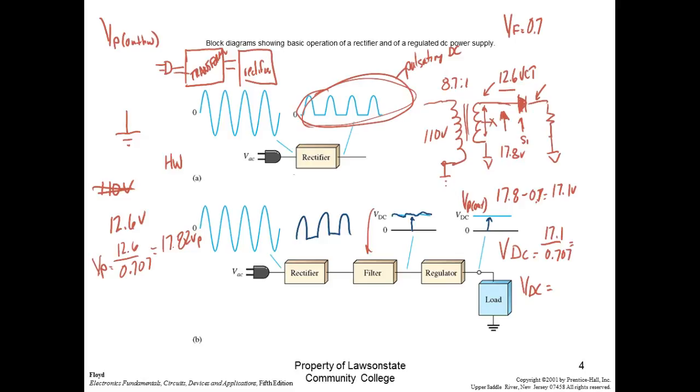So normally what happens is we have opposition down this circuit. If my load pulls more current, then everything down here would try to drop more voltage unless we have a regulator which is going to maintain the output. So when we say unregulated power supplies, that means if you put a load on it, the voltage goes down. If you take the load off, the voltage goes up because of Ohm's law, right? V is equal to I times R. So this is what we're working at.